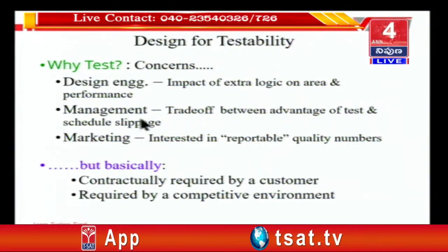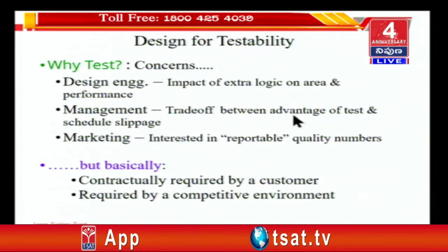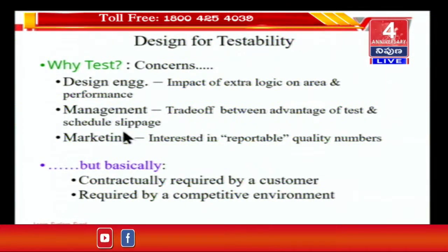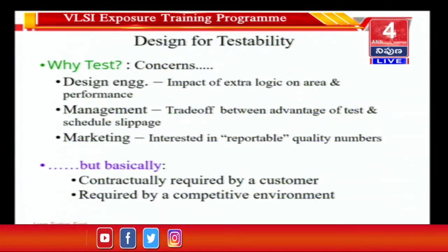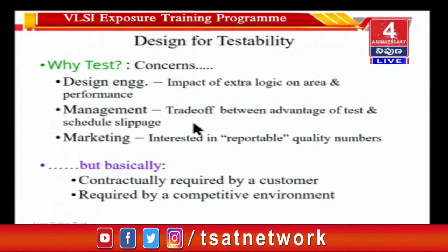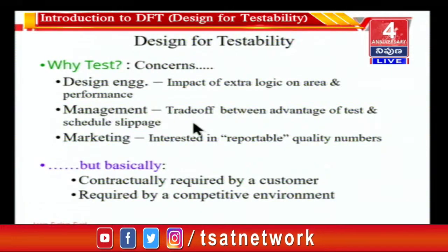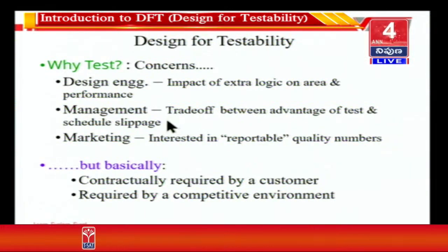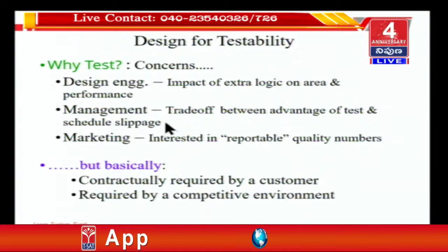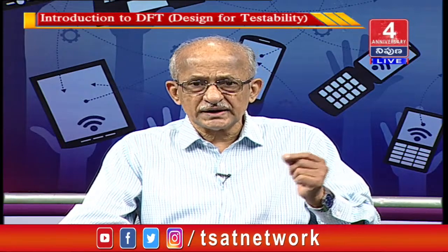Management will say there is a trade-off between the advantage of test and the schedule slippage. So basically DFT engineers working on a particular chip may work for maybe a month, 2 months sometimes, just to make these changes for testability. Not only that, they need to come up to certain expectations of coverage figures. Now different types of faults are there in the circuit. You need to uncover, you need to detect and say that none of these faults exist.